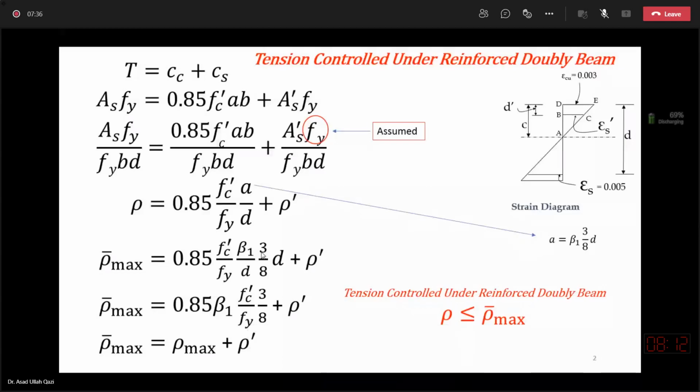When I'm talking about these types of doubly reinforced beams, I am silent about the compression steel, because compression steel yielding or non-yielding does not affect the ductile behavior or the tension steel strains. So the classification will still depend upon the status of the tension steel.